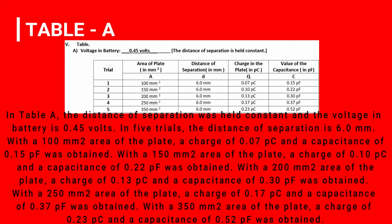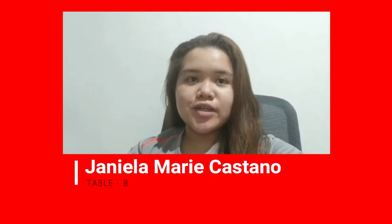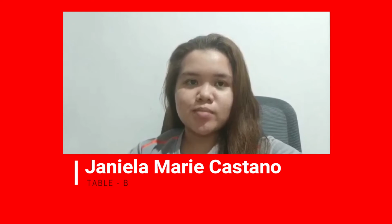was obtained. With a 150 mm squared area of the plate, a charge of 0.10 pC and a capacitance of 0.22 pF was obtained. With a 200 mm squared area of the plate, a charge of 0.13 pC and a capacitance of 0.30 pF was obtained. With a 350 mm squared area of the plate, a charge of 0.23 pC and a capacitance of 0.52 pF was obtained.